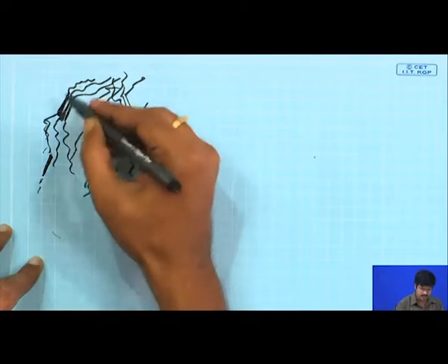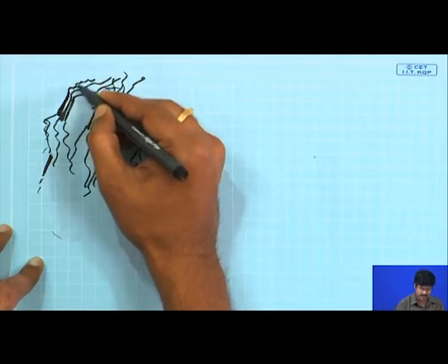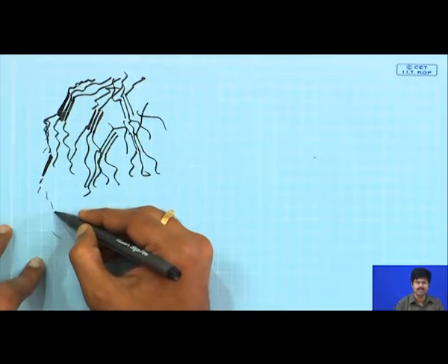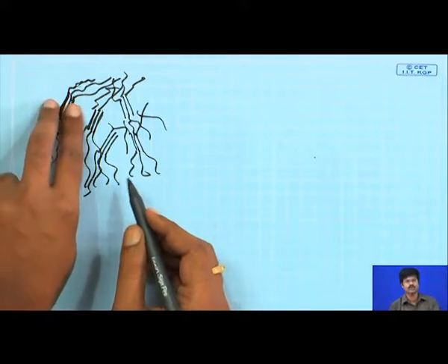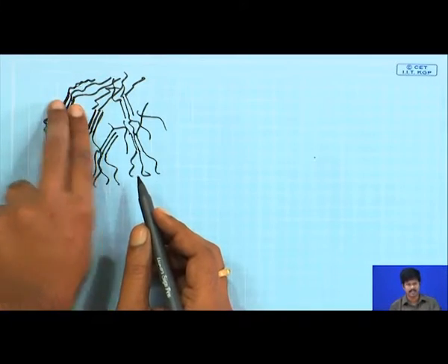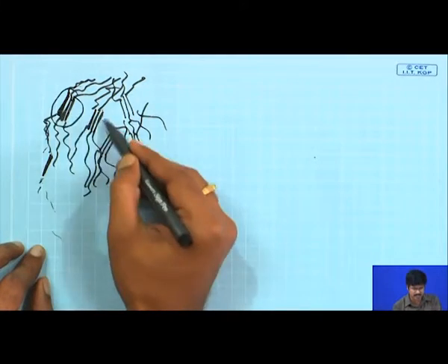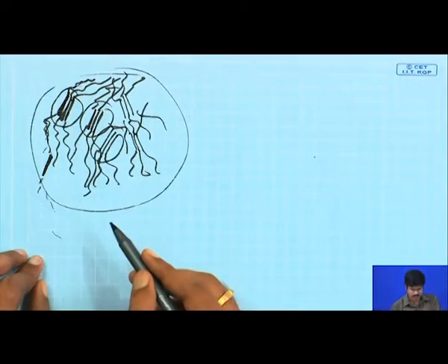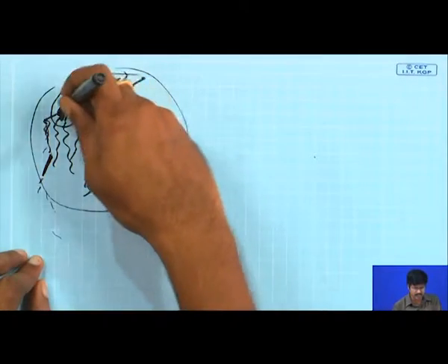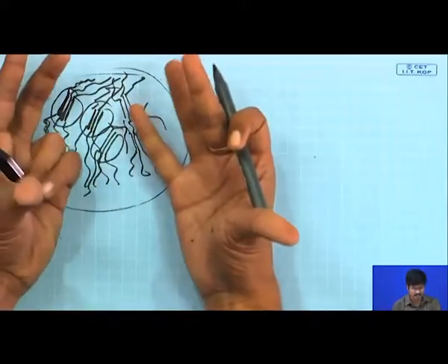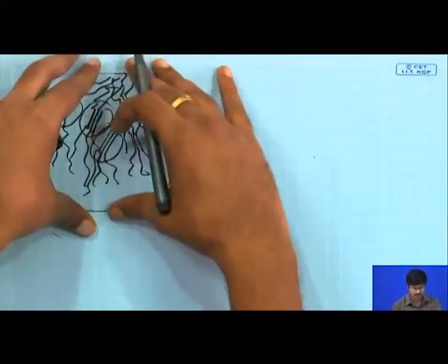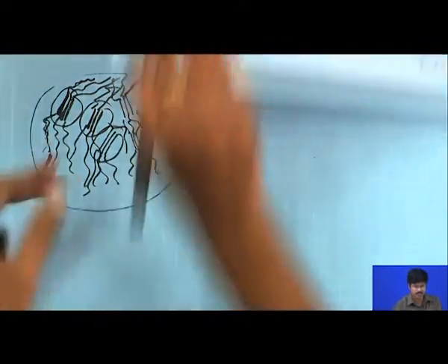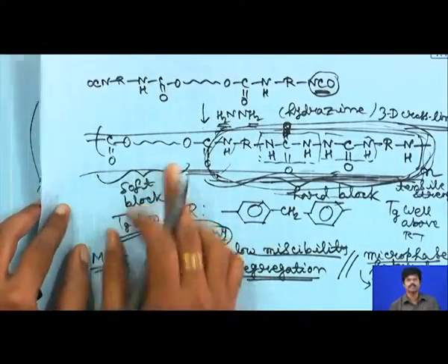In this polymer molecule, you have a hard domain and then a soft domain on this side, again another hard domain, another soft domain, like this. The point is that the hard domains will come together through hydrogen bonding interactions. So, they basically provide 3D cross-link centers for the whole system, and these cross-links are present in the material, which has what you call a soft matrix, made of these flexible chains, which are basically your polyester part, all right.